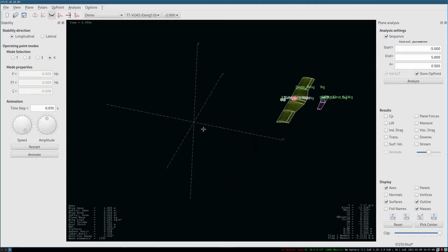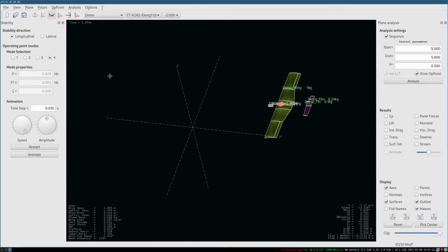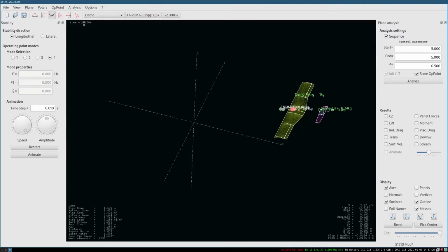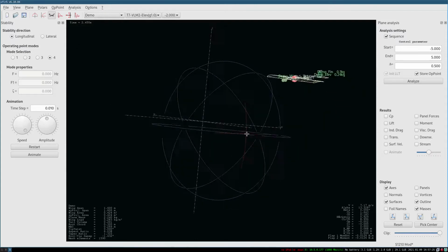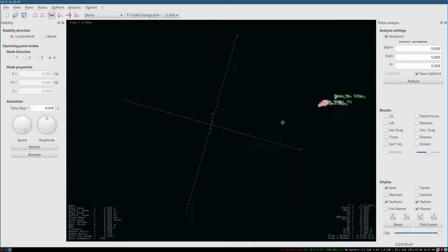So that's not something to worry about. And while it's an instability, the reason it isn't something to worry about is typically the time involved. If you measure up this aircraft, we've really only moved about 1.5 meters in about 2-3 seconds. Considering a flight speed typically is going to be 10 to 12 meters per second, in this case it's only 7, but considering our flight speed, we're talking about a very small amount of deviation from our flight path, and we haven't really lost altitude. In fact, in this case, we're actually gaining altitude more than anything else. So as long as these modes happen slowly, and as long as you have many seconds for a pilot to respond to your aircraft.